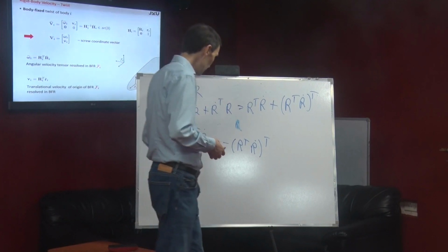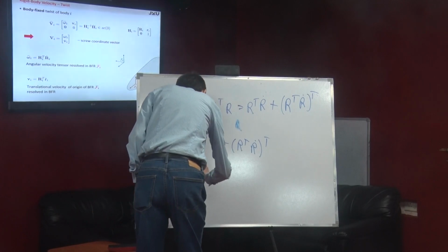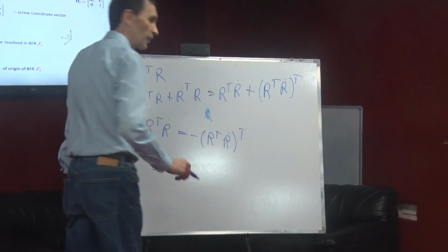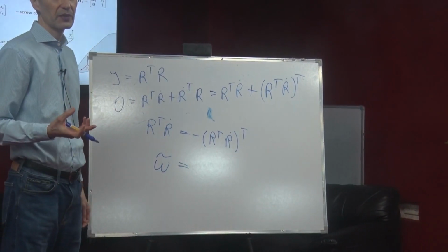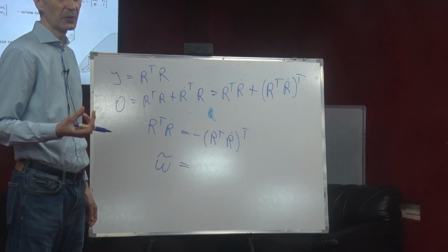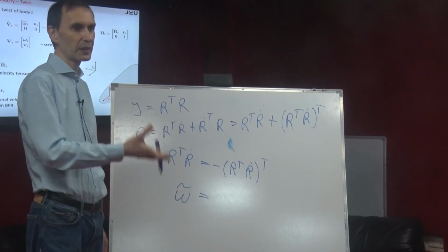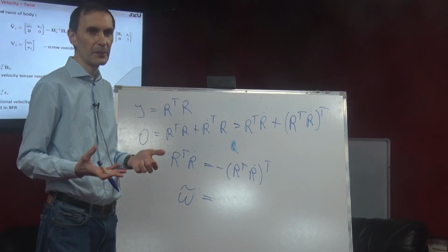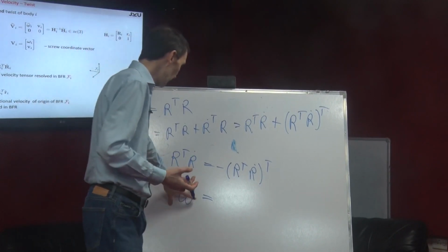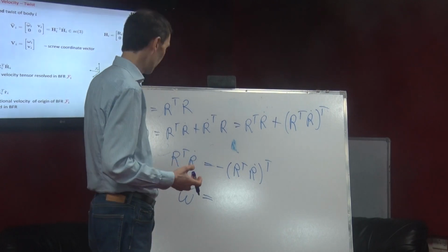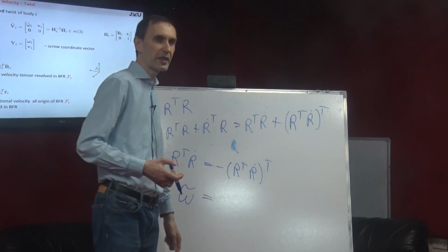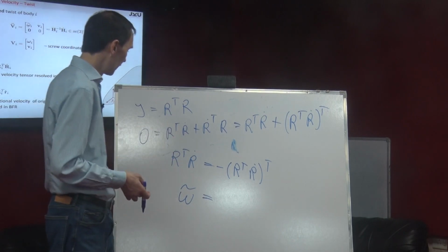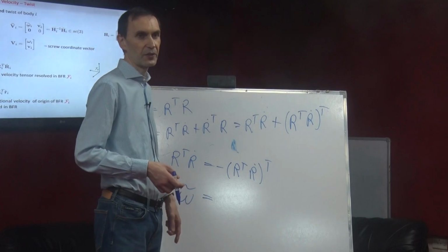So if I know it's skew-symmetric, then I can say there is a vector that defines the skew-symmetric matrix. Because for any skew-symmetric matrix, there is a vector. Or the other way of saying it, any skew-symmetric matrix is defined by a vector. And this vector is given a name and a physical meaning, and we can show why it has the meaning, which is the angular velocity.